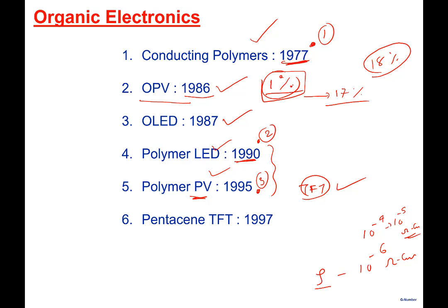You could get a thin film of an LED, or a thin film of polymer as a photovoltaic cell, through a very simple technology. You don't require vacuum evaporation, where you have to put the material in a crucible, put it in a vacuum and all that. You could just do it by solution processing. So the importance of polymers is solution processing. Your starting material is a solution.